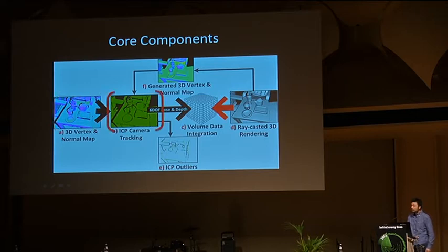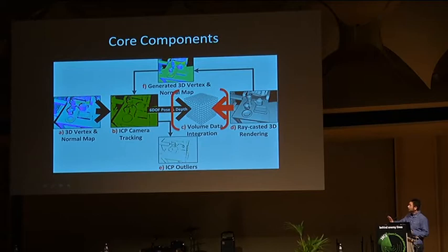And then based on the point clouds of the current image frame and the previous image frame, we compare the relative spatial offset between the frames. And then once we know the 6 degrees of freedom orientation of the camera, we can then actually integrate the depth data in a global volumetric data structure. So this data structure doesn't only contain the 3D point cloud of my current view, but it stores, memorizes all the scenes it has seen previously.